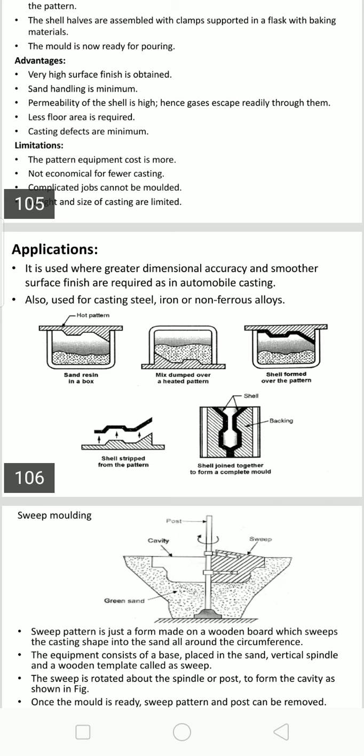The next step is obtaining and stripping the shell. The pattern plate with the adhered shell is removed and heated in an oven for 2 minutes at 300 degrees centigrade. This is exactly what is called curing.